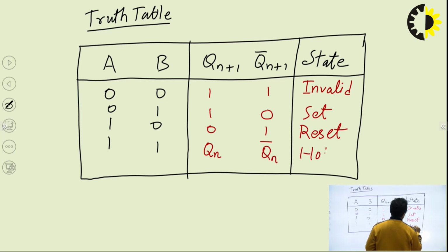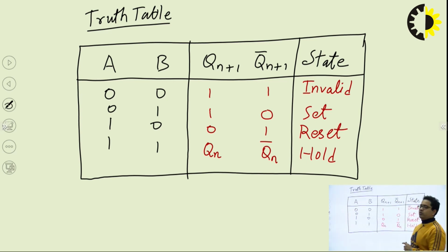Now once we have drawn the truth table, we have to assign the names to A and B. And in the case of a NAND, we have considered the value for which we can easily predict the output is 0. So that means we have to concentrate on the input combination zeros. And in the earlier case of the NOR gate, that is a latch using NOR gate, we have discarded the equal combinations, meaning giving the same value to the input terminals. We have discarded those combinations.